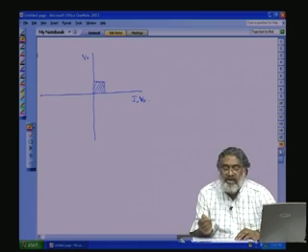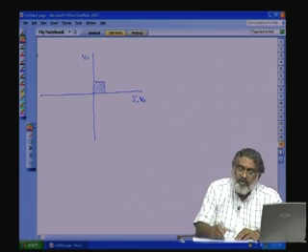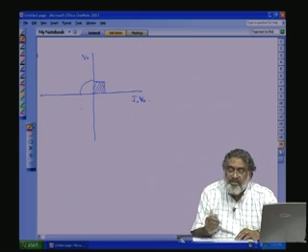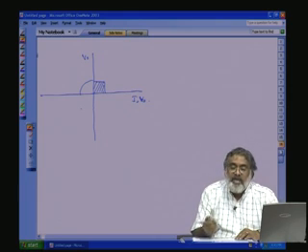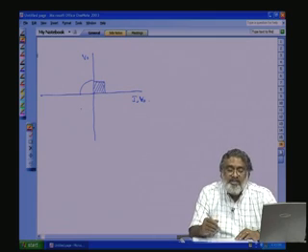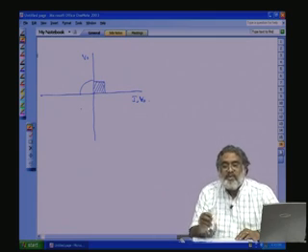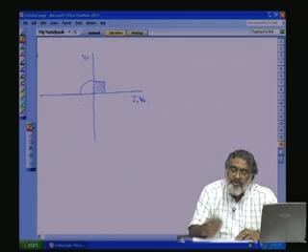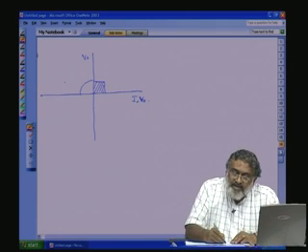But in many drive applications we require all 4 quadrant operation. That is this one, where voltage is positive and current is negative. What is meant by that? The net power is negative. That means the load is sending power back to the mains. So a motor system, when it is rotating, the stored kinetic energy will transfer back to the source and the system will decelerate.